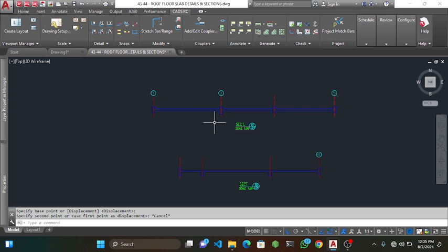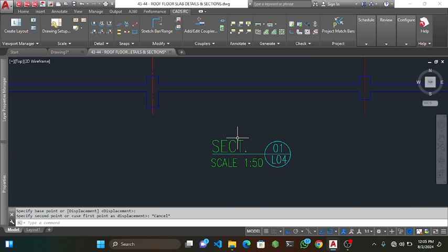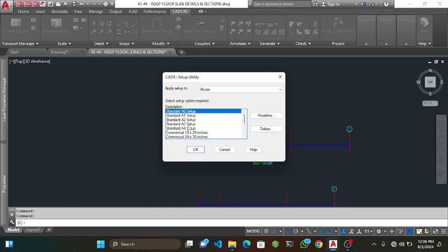So just like I always tell you, the first thing you do, for this drawing, you see it was done on a scale of 50. This was done on a scale of 50. And normally I use a text height of 2 times my scale, which is probably 100 mm. But in the previous video I mentioned that for your text height it's always 2.5